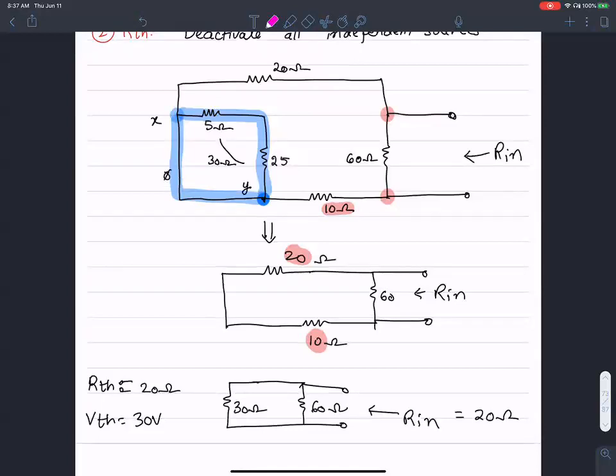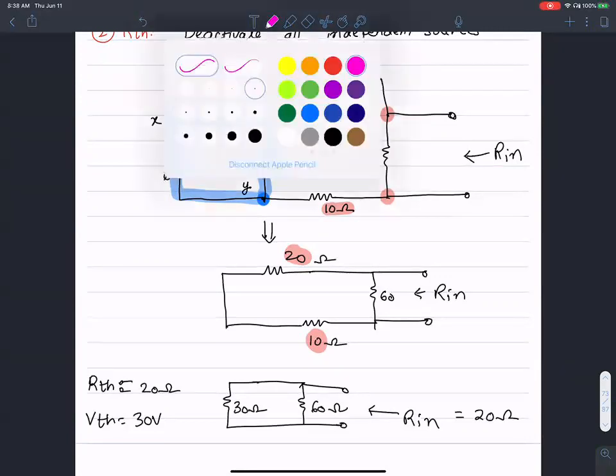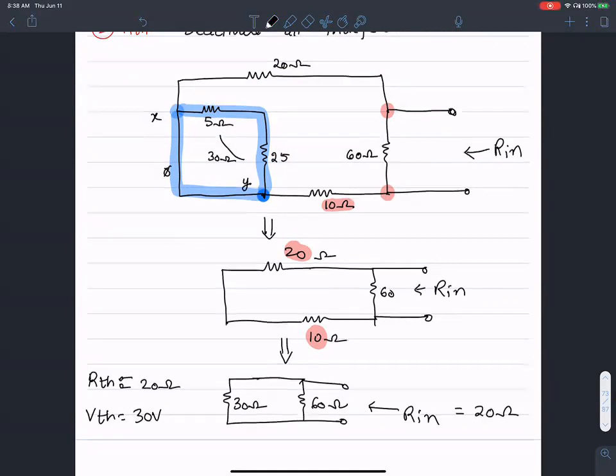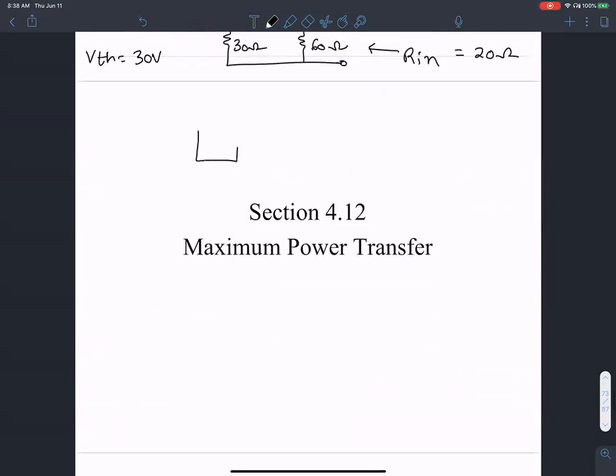Questions, please. So is this generally used on really large circuits where you can take a portion of it and simplify it? Yes, yes. Also, if you have a black box kind of circuit, and you're trying to connect a load to it, and you want to match the impedance of this guy, the internal impedance, to this guy, you have to have a way of expressing large circuits in the form of a Thevenin equivalent, just so it's easy for you for further analysis.